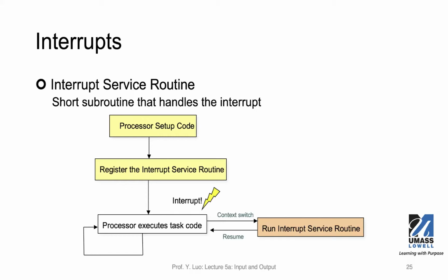You can have a certain program logic within the ISR, but you should not have a very long subroutine that will take extended time. The main purpose of this ISR is to respond to this interrupt. Again, the actual operation will be certainly different from case to case, but the main purpose is to deal with that interrupt.